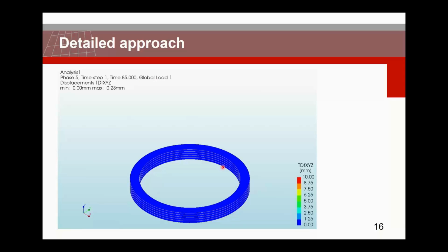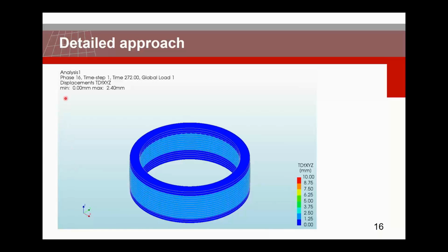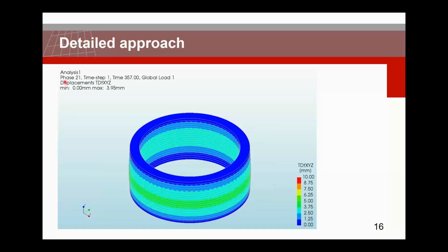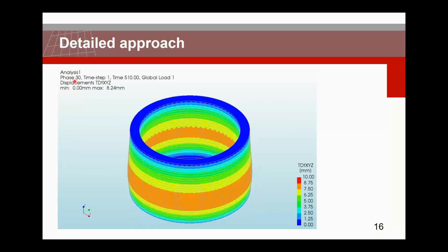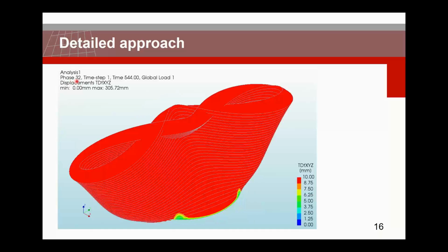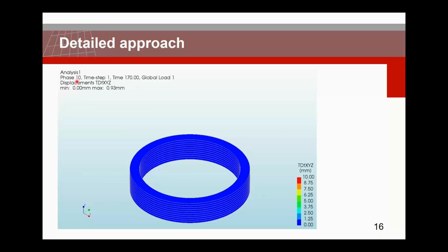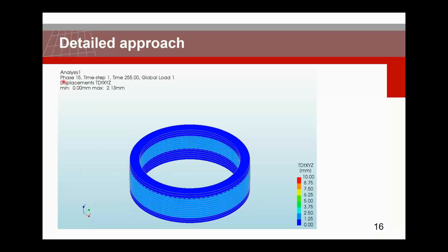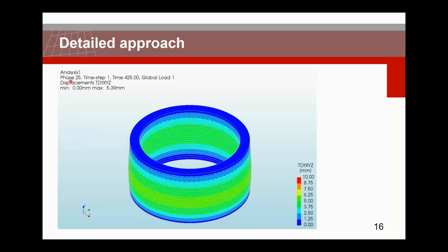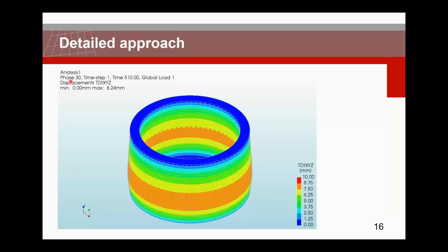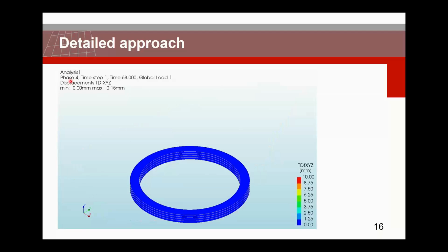You can also see that in the Diana analysis. If you look at the top left of your screen, you can see the phase number that's equal to the layer number. So at layer 32, the final layer, we see divergence of the analysis. That means we see failure. You can also see that from about layer 15 to 20, we can see the deformation of the cylinder.